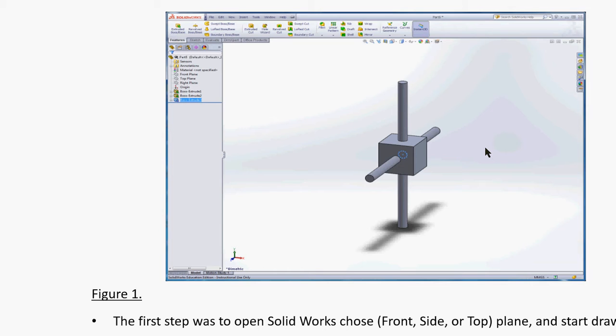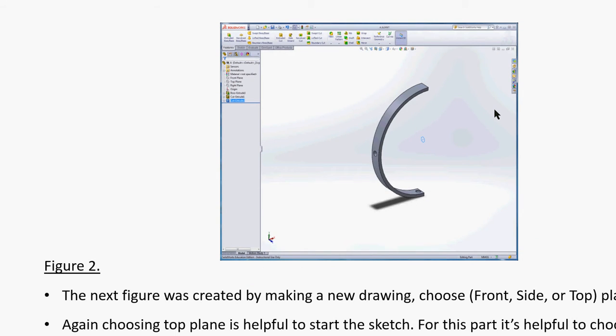In this case, we do the sketch so that with a rectangle you extrude and form the part, and from a plane you can draw a circle from the side and extrude the parts to make these rods. That makes the basis of the universal joint.